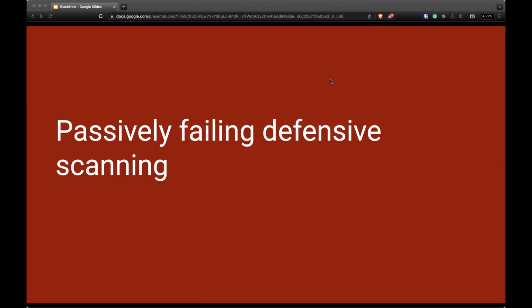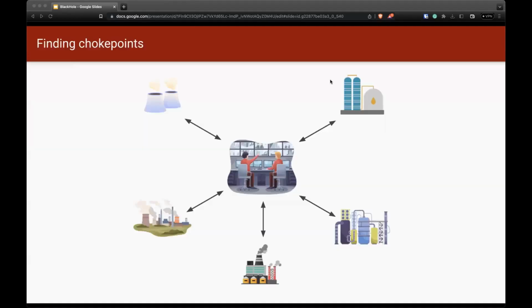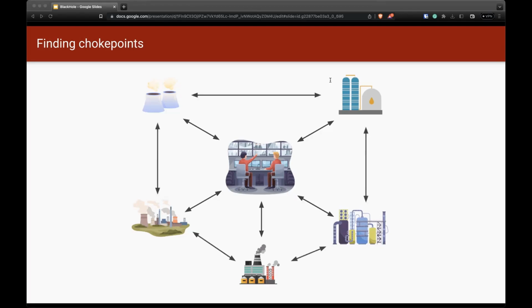But let's take a closer look at this. Suppose you have a SCADA system across multiple sites where all the communication is backhauled through the control center at headquarters. In this case, all the core or distribution switches are on hand at the headquarters, so at least you can see traffic from devices that communicate beyond their site. Now consider a scenario where site-to-site communication is not backhauled through the control center. This is operationally more efficient, but it also makes it much harder to set up a passive network monitor. If you have hundreds of sites, it will be impossible to get a full asset inventory.